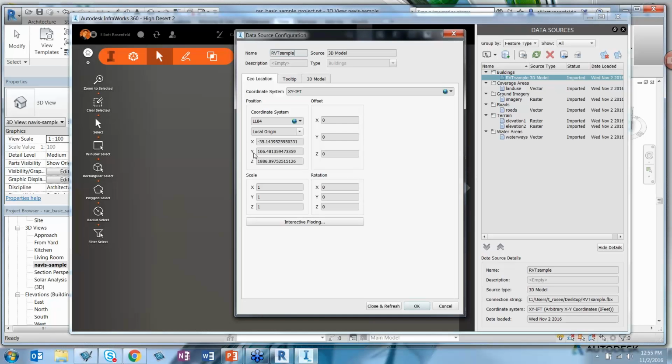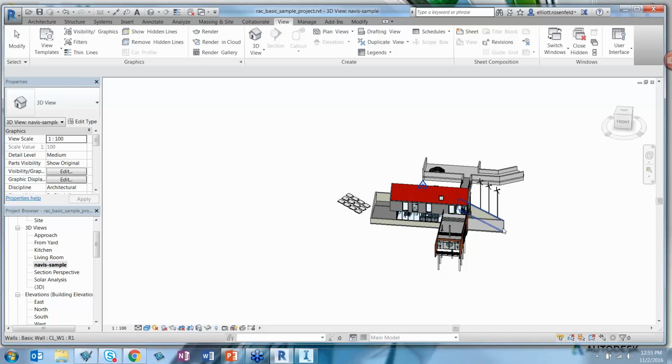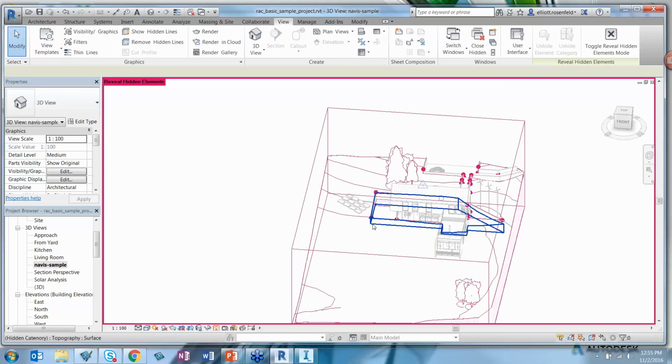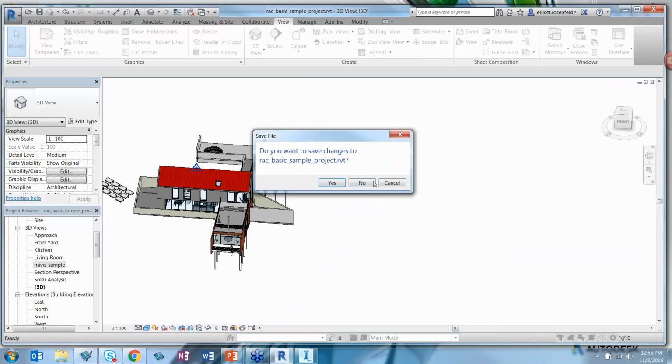Well, okay, so for starters, when you're here in FBX and you bring in your 3D model, you're going to want to use your latitude, longitude, and elevation from your Revit project site, which I'm moving a little too fast to demo effectively, but this will work. So let's unhide my project-based point. And I'm going to actually just recreate this model super quickly.